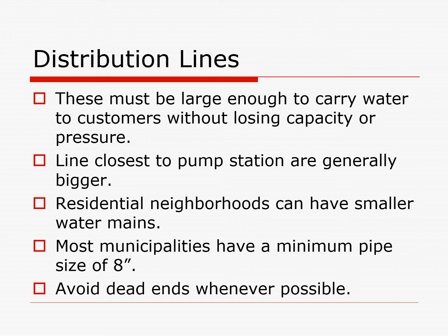And I could tell you that there are many neighborhoods, especially older neighborhoods, that have smaller water lines than the minimum of 8 inches that is required now. Many of them actually had 2-inch water lines. And one of the things that I was trying to do as the engineer was eliminate those 2-inch water lines as much as possible. And we would design and ask in our budget to replace a certain amount of those pipes every year so that we can get our system to run a little better than it did.